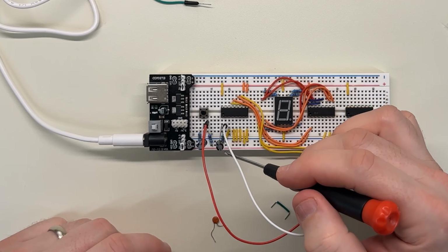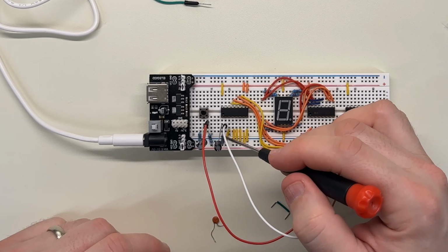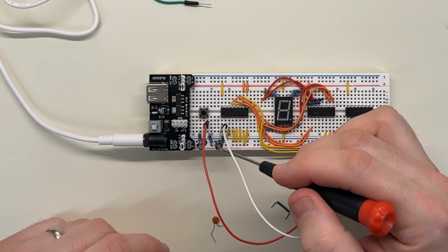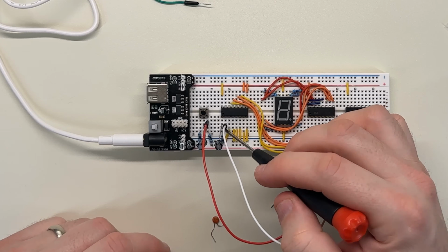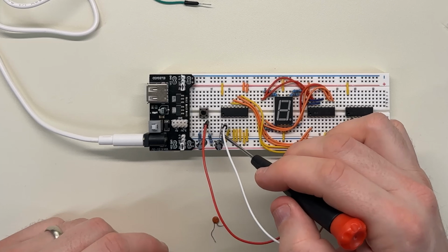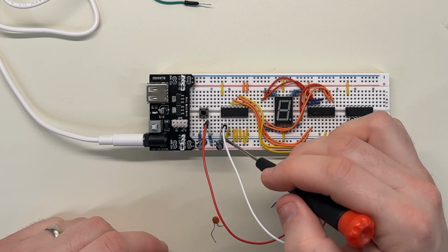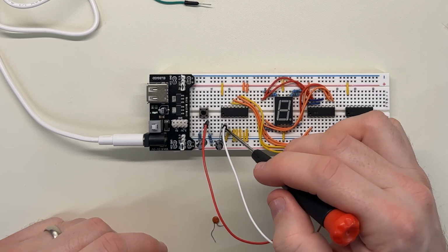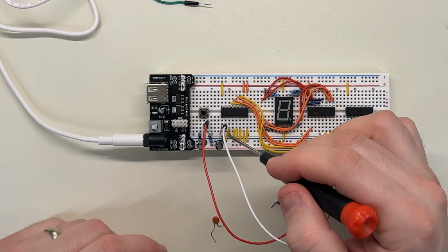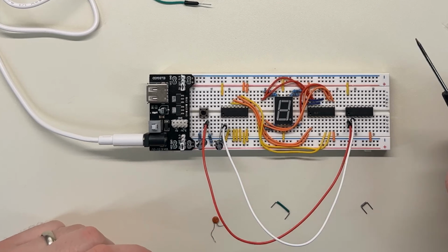It's just that because of the way these resistor capacitor circuits work, as the capacitor charges up when I first turn it on, that causes this voltage here to be low initially and then build and build and build as this gets full. When it gets totally full, current essentially is going to stop running through here, but this is being held high then, which is exactly what we want. We don't want it to be in reset. We want it to read as reset initially when we first turn on, and I think that's what this does.